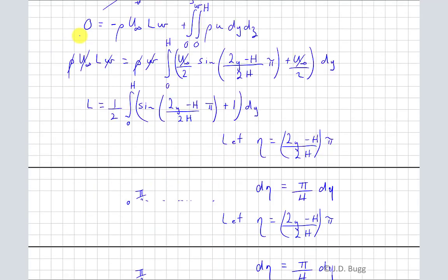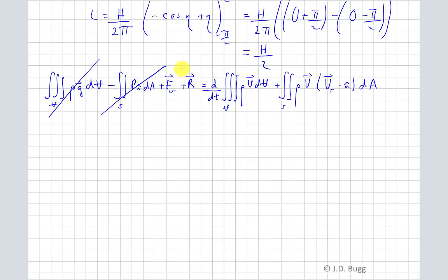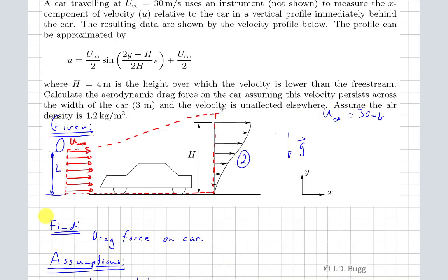So I cross that off. Next thing is the reaction force. And again, reaction force is the force by any solid member cut by our control surface. So notice the only place where that's happening is where the wheels touch the ground.